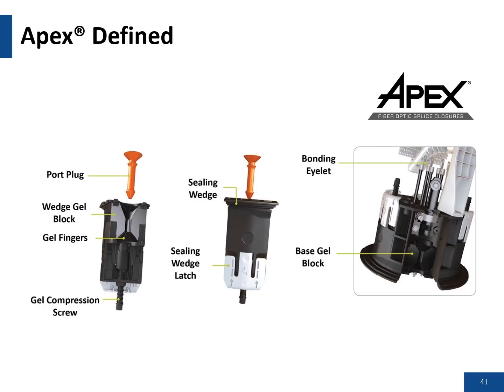Therefore, if you're going to add a cable to a closure, you don't impact the existing cables that are there. But all this is to assure that you protect the splices, whether they're stored in an aerial environment or in an underground handhole, and that the closure doesn't become an ingress point for moisture that may impact the fiber technology.